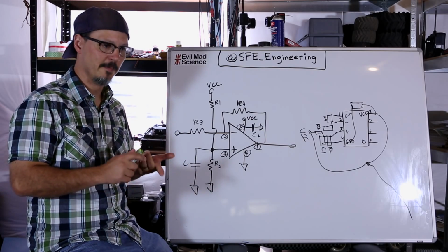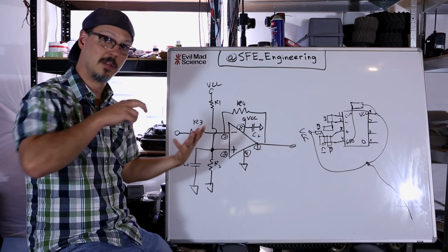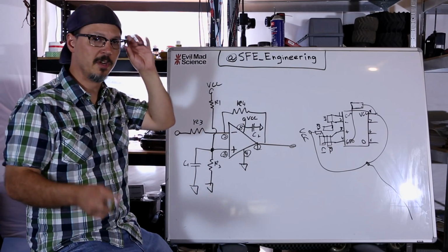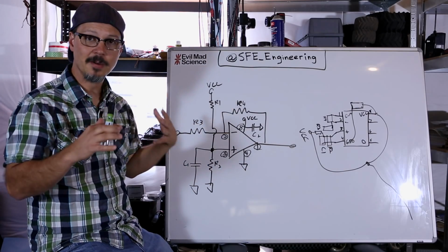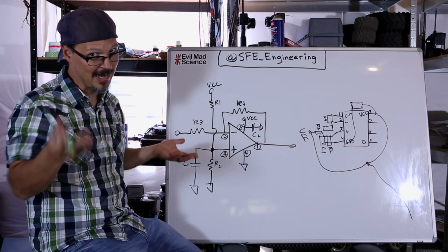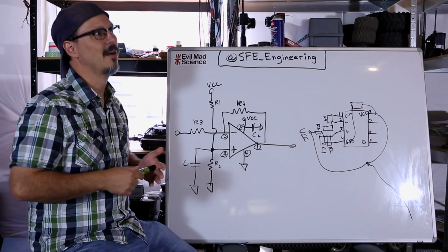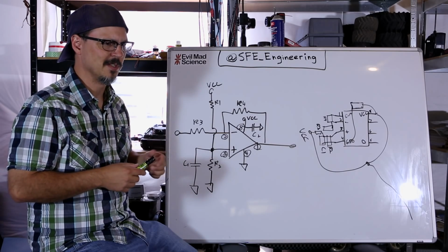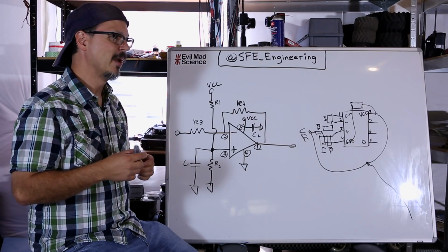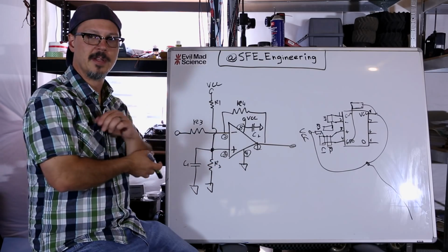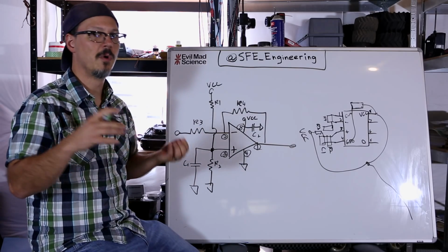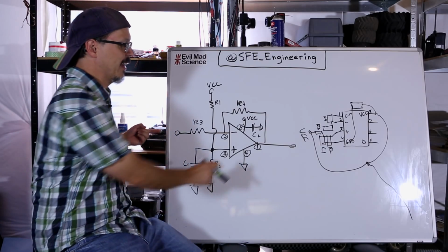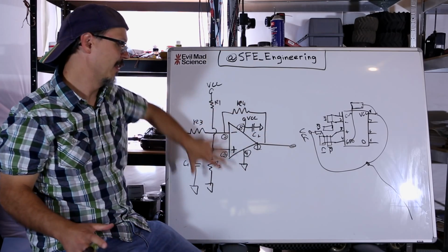You want to keep the components that are close electrically, close physically. So, for example, like I was showing you on the microcontroller, you want to keep those decoupling caps very close to the pins that they have to act upon. In the case of sensors, same thing. Decoupling caps are the biggest ones I'm probably going to talk about. But any resistors that have to do with the particular components, you want to keep those local. Any traces that are not the input and output to the section, you want to keep all that stuff close.